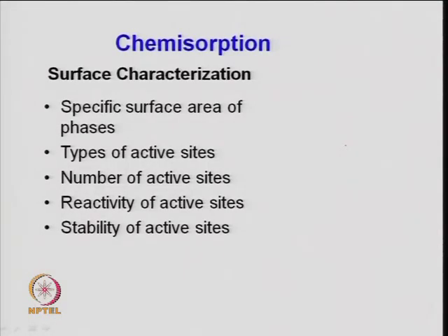So, you have seen the BET surface area, and then determination of pore size, pore volume, thickness of the layer, and adsorption hysteresis, based on the nitrogen adsorption desorption isotherm, and that is the case of physical adsorption. So, that just talks about the textural property of the catalyst. Morphology can be evaluated in terms of spherical shape or particle size, the crystalline size, crystallinity. There are other methods which we will talk about, based on the X-ray diffraction patterns, and